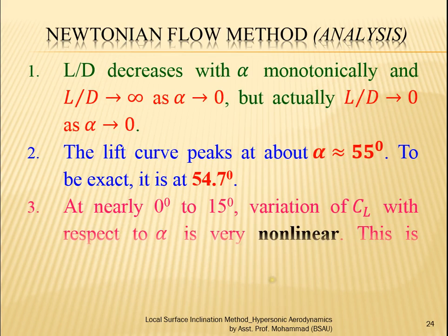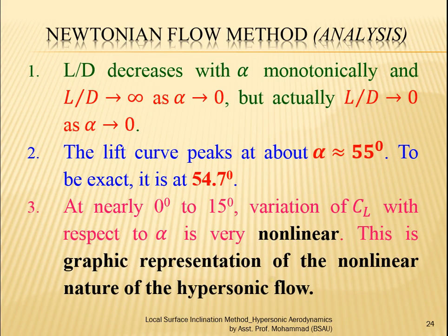The third observation we can make here is that at nearly 0 to 15 degrees, the variation of CL with respect to alpha is non-linear. It's very non-linear. This is a graphic representation of the non-linear nature of hypersonic flow. We actually started this module by talking about the non-linearity of hypersonic flow. That's a very comprehensive idea.